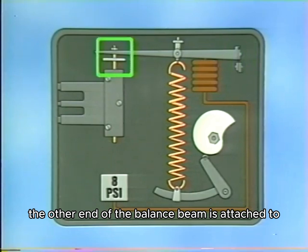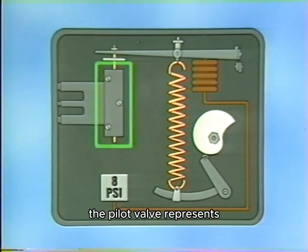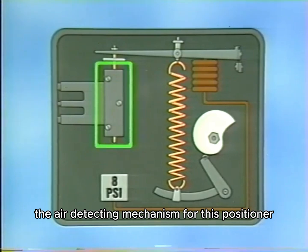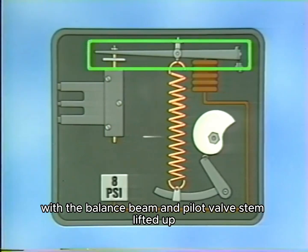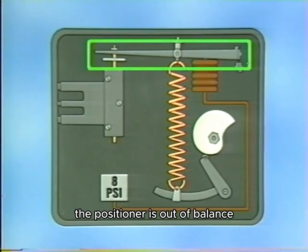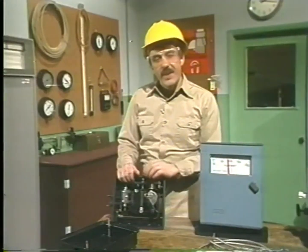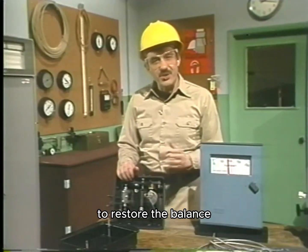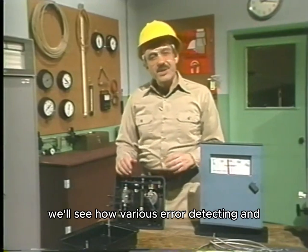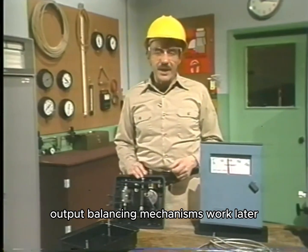Now, the other end of the balance beam is attached to the stem of a pilot valve. The pilot valve represents the error detecting mechanism for this positioner. With the balance beam and pilot valve stem lifted up, the positioner is out of balance. At this stage, the output balancing mechanism comes into play to restore the balance. We'll see how various error detecting and output balancing mechanisms work later.